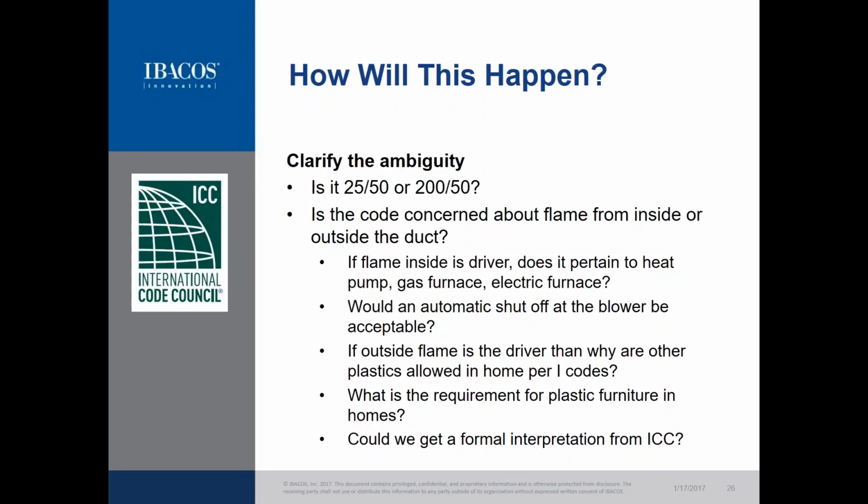So, going back to this whole issue of what's the aim and goal of the code, and that's to ensure the life safety of the occupants. To do that, related to plastic ductwork, we really want to understand what is the fundamental issue and basis around why the requirements are what they are. What's the concern related to combustion? Is it a concern of flame inside the duct system itself? Is it a concern with flame inside the house?